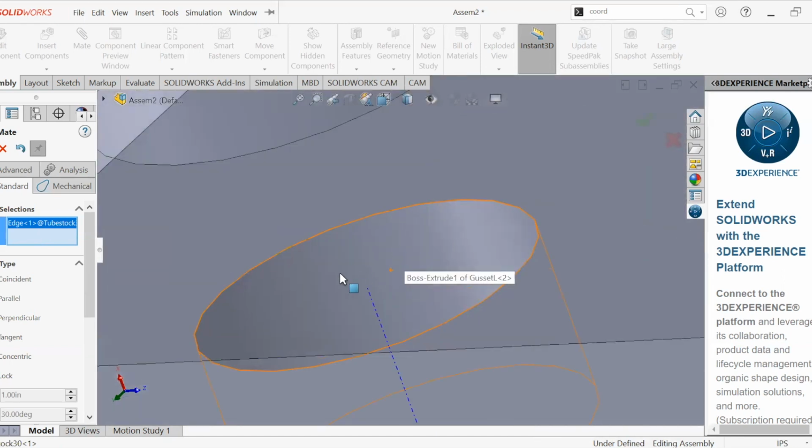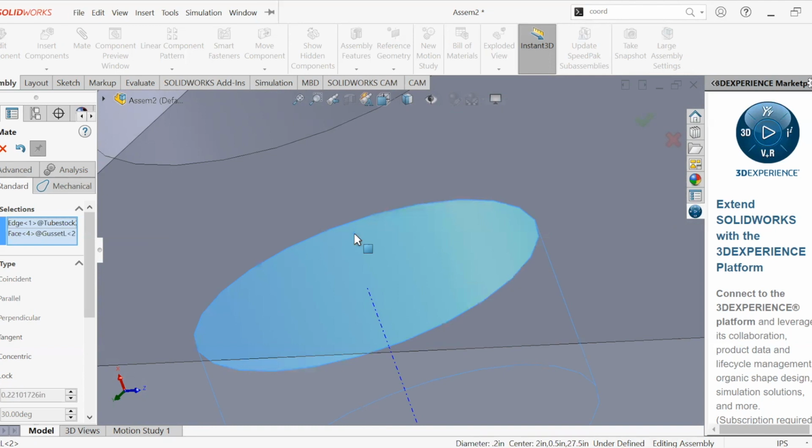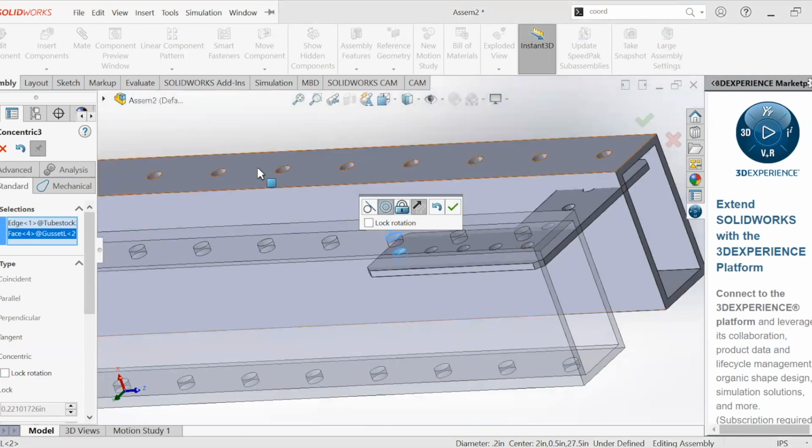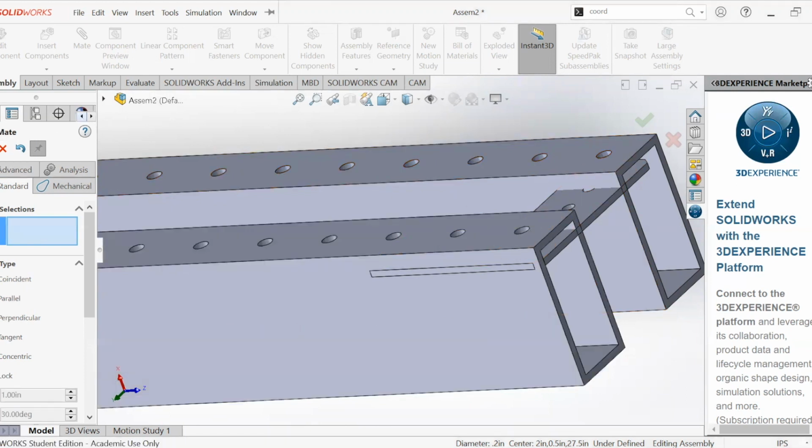So we always want to have as many restraints as possible without over restraining it. At the same time, you want to keep it to a minimum. Don't overdo your restraints because, like always, we want to keep everything as simple as possible. But make sure you have enough so that your part is completely defined.